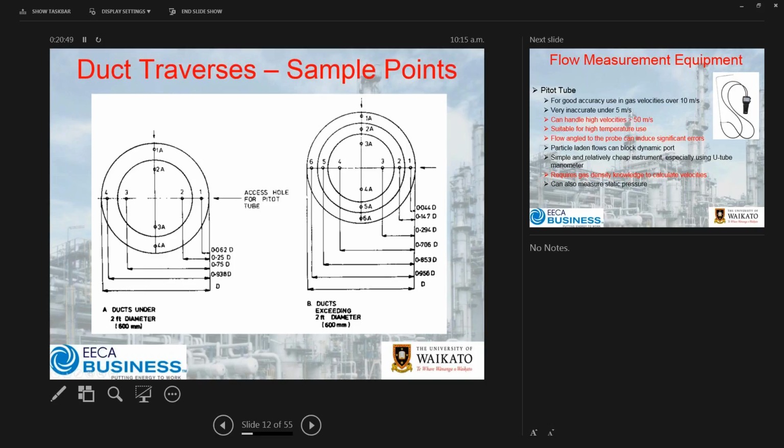typically is they'll come across the duct at an angle, and you'll typically find for a larger duct you'll have 3 holes on the extremities out here and then up here as well, kind of mirroring 1, 2 and 3, and then 4, 5 and 6. But whereas you've got 2 here, if you're wanting to be super accurate, you could have 2 annubars perpendicular to one another. Most installations tend to compromise and have one just across the duct at an angle.